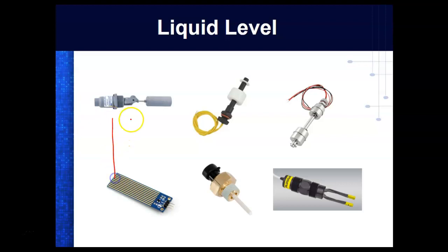On the aircraft, we'd have two tubes that would go down, an outside tube and an inside tube. They were capacitors, and the fuel came up between the two to change the capacitance. That's the way ours worked. I don't know what other airplanes were. Most times we had about three across the top of the wings and three on the bottom, and they were all averaged together, so no matter what altitude the plane was at, it gave them the right fuel reading.